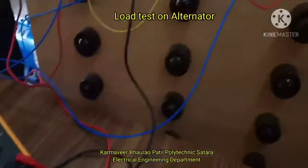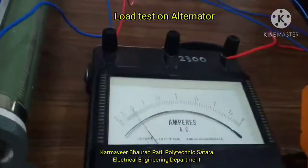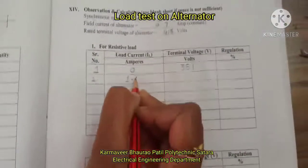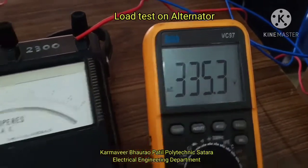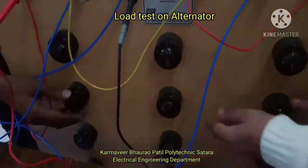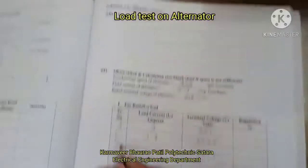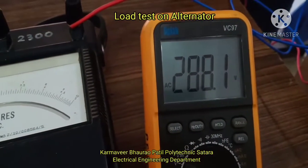Now we'll make the load on. The AC ammeter will be showing the load current. It is 1.4 and voltage is 334.7. Again increase the load. Current will be increasing: 2.6 ampere, voltage is 288.